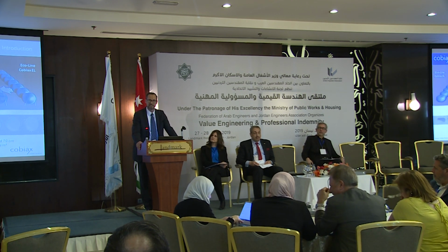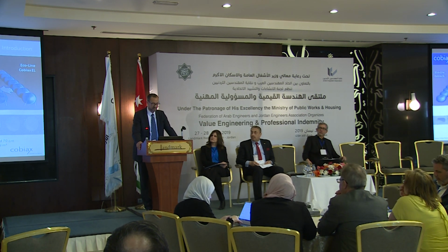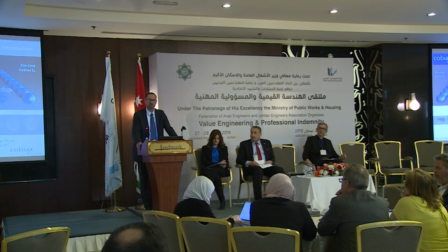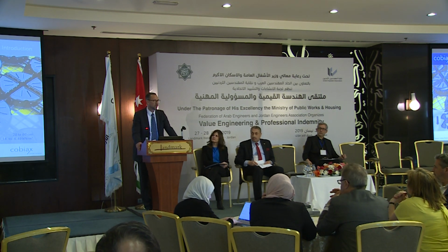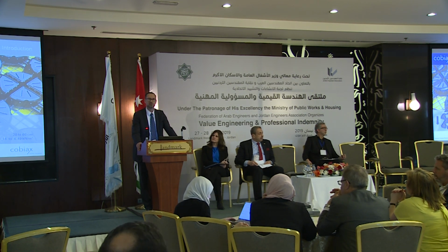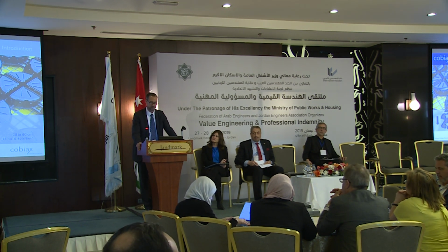So we have sizes that make it possible to achieve slabs between, in this case, 22 centimeters and 70 centimeters, and we come up with a weight reduction between 130 kilos and nearly half a ton. We also have a newer system where we can start with a slab thickness of about 20 centimeters and go up to a slab thickness of 80 centimeters, with a weight reduction between 114 kilos per square meter and up to 650 kilos per square meter.